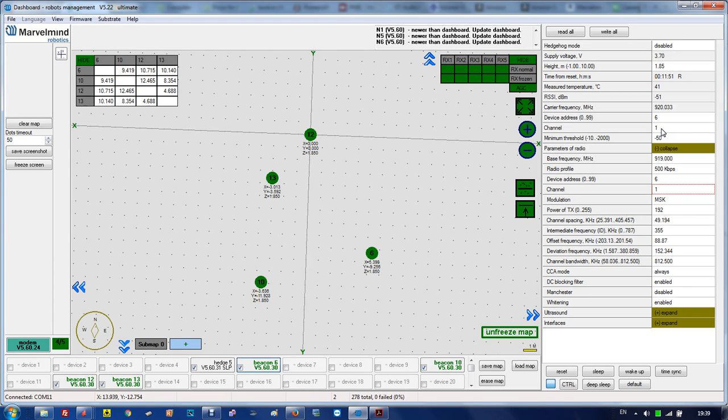It's basically channels. So you can set up several systems, and the systems will not know that they coexist. They will operate on absolutely separate frequencies. So if you have two systems, two modems, you can run them. But remember that they will not know about each other in radio, but in ultrasonic they will interfere if they are in the same room. So be careful. You can deploy in different rooms where the ultrasonic signal doesn't propagate from one room to another. In this case, 2, 3, 4 systems can coexist very easily.